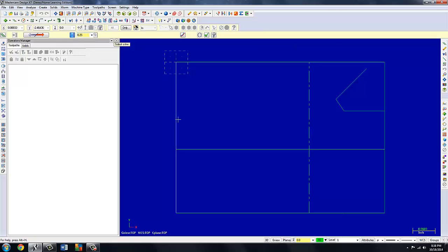From here, 250, apply, 95, enter. From the bottom, 950, apply. And my vertical lines for these angles and intersections are 2.245, and that's coming off the center, and 2.5. I forgot to apply it, so now I'm going to apply the 2.5. I'm going to go back and put in the 2.245. Pick a line, pick an offset direction. There we go. So I've got those lines put in, and now I can drop in some of the angles